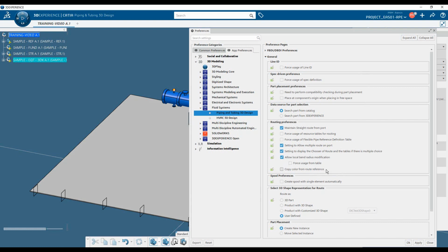So the recommended options that we usually use are those ones. Afterwards, depending on the context, you could decide to deactivate some or activate others. For example, in a piping context, this one is not really required. We don't need to have starting straight lines. This option is much more used for small tubes like hydraulic tubes, things like that, which need to be bent on the machine. So to start, we are going to deactivate this one.